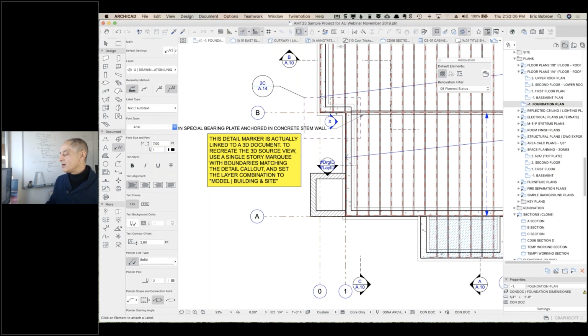Sorry. The way that you'd have to do that, yeah, you could do things with morphs. You can do some things sometimes with just subtractions. So you could use the grid tool, or the grid element in ArchiCAD, there's an object that's a grid, and you can say, I want to put a grid that would be, at least at the beginning, a bunch of thin members, thin elements, and then use that as a subtraction if you wanted to have little grooves.